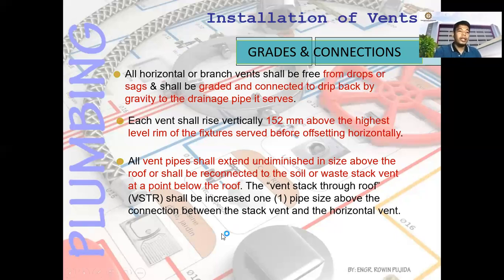So for the connection of the main, the VSTR, the vent stack through roof, normally in construction we'll have 0.3 meter above the roof.